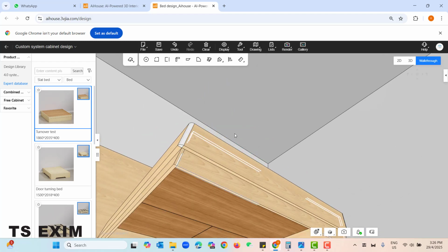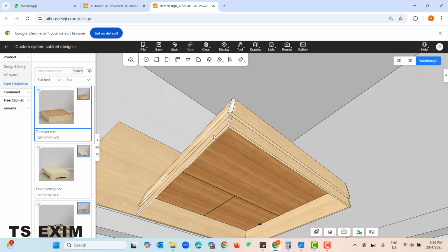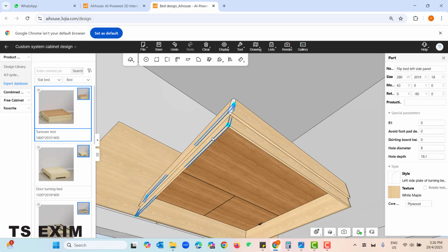Okay, then this one I will move inward. Okay, all the corners here I will move inward. Okay, this one you can select and you can move forward. So here you need to go to movement. Okay, you can see got size, movement and rotate category here. You can go to movement. Okay, to move forward you can plus. So I will move forward 100 mm, enter.